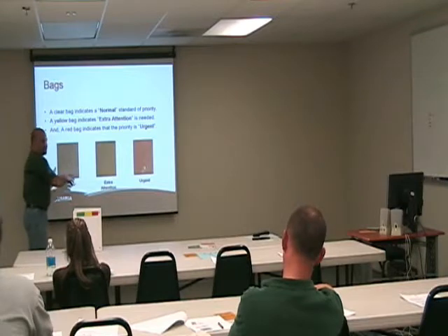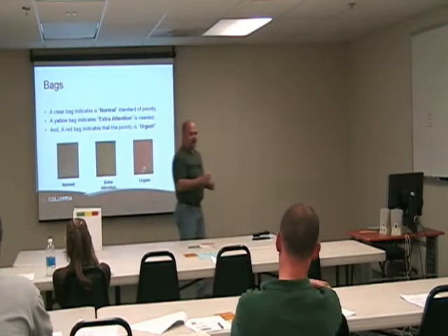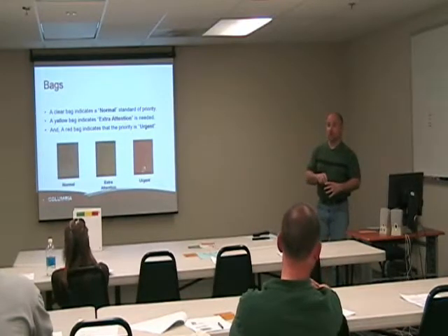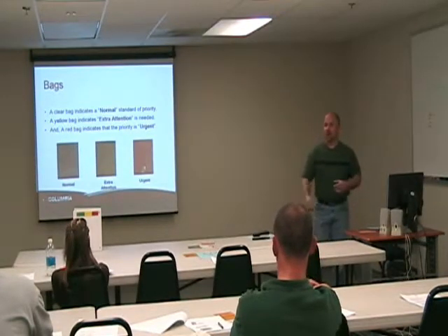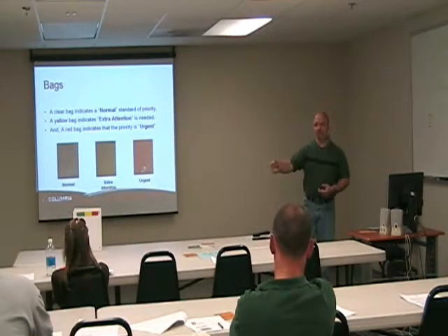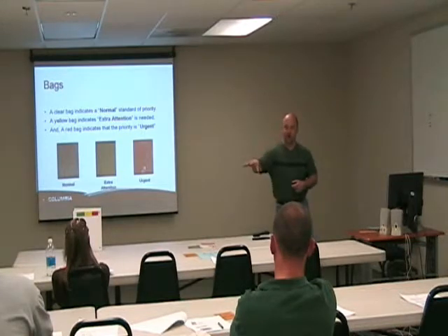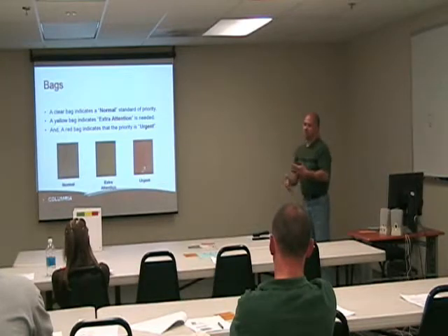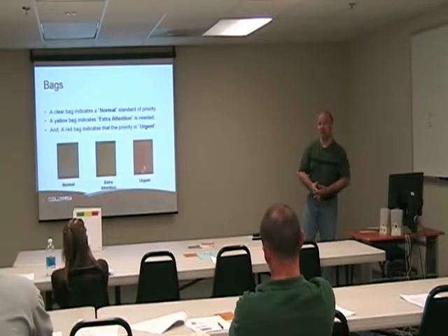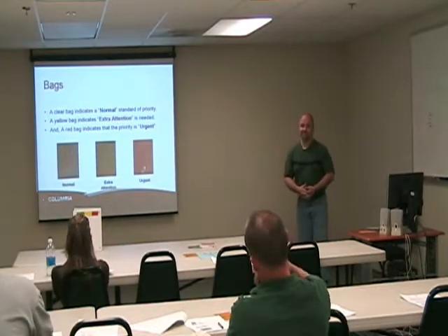Now here's the downside of this system compared to a post. At the point of conception of the needed part, we will put the work order in the Kanban card in its bag, clip it to it, and send it out. We can't update that. So after it's out, it's whatever priority the bag is. But say we get 2 more requirements after that part has gone out. Those are yellow. Well, they can't exactly go out and necessarily find that other part in its process to change bags on it. So it gives us a way to determine the priority of the parts, but it's not as real time as a board post is. But it's better than nothing. Any questions?